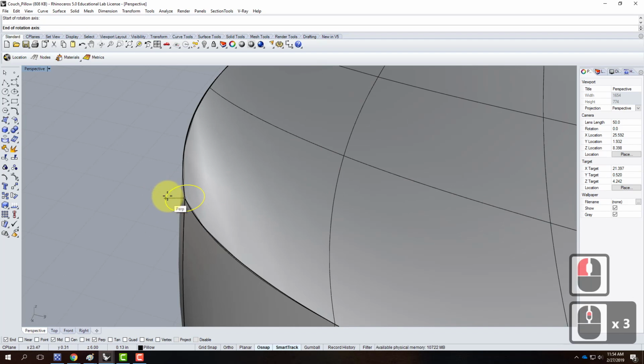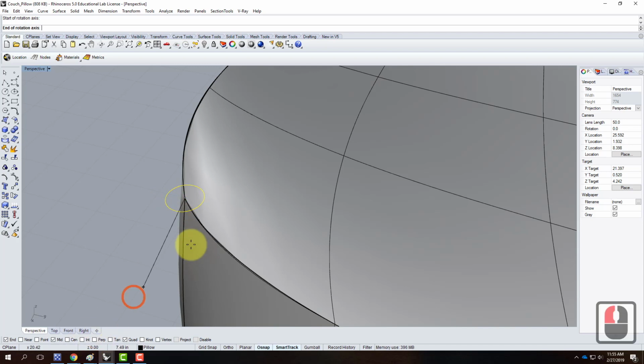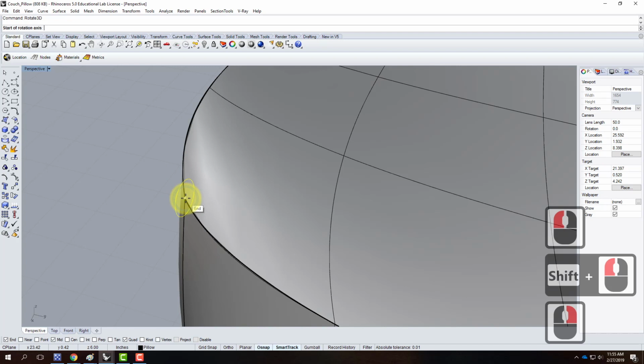If you're struggling to see that, you can also turn on Quadrant Snap. And it should allow us to snap to quadrant. There it is. Let me turn off perpendicular for a second. There you go, quadrant. And you can rotate it in groups. So I'll rotate it up first, and then I'll rotate.